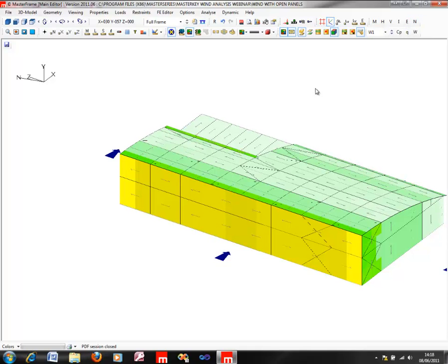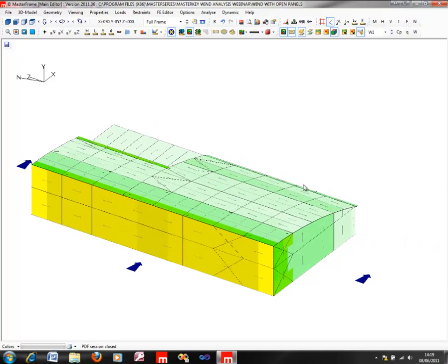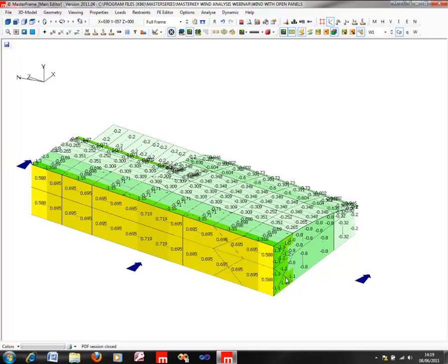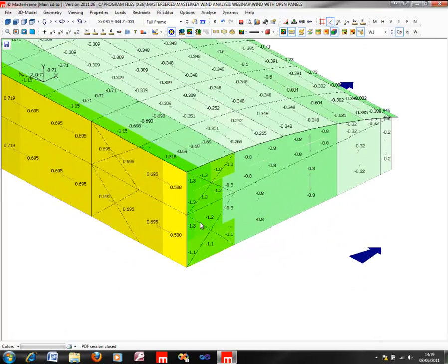So we've got simple color coding going on here, which represents greens for suction, so heavier shades of green for heavier suction, and then also we have yellows and oranges for the pressure values that we see there. So I can view my coefficients of pressure. I can see my positive values in this region and my negative values around in this region. So I can see quite clearly my zone A, B going probably to CD zone down in this end.